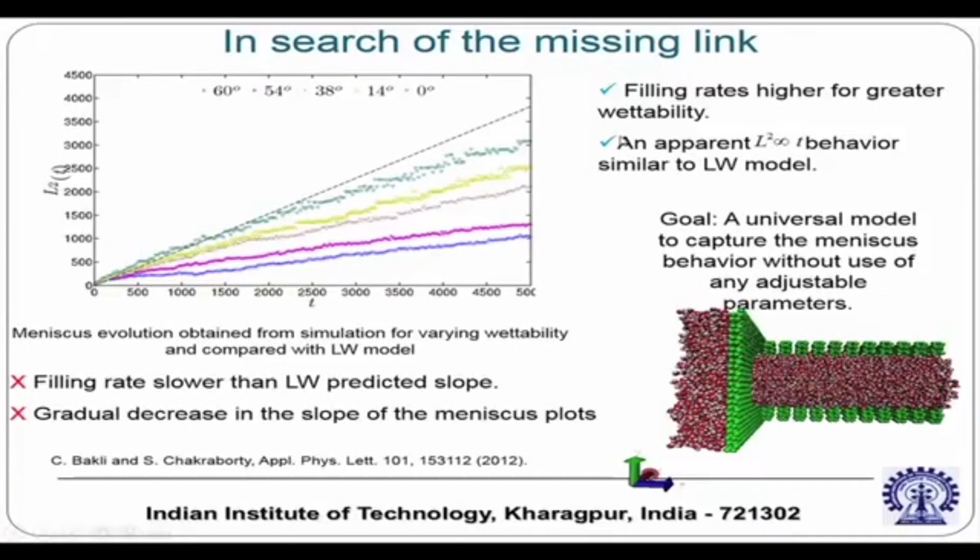However, one has to keep in mind that although the capillary action is stronger, you also have a resistance force, and the resistance force will depend on the slip, and slip depends on wettability. So it is a complex coupling; you cannot just give reasoning from a straightforward intuitive argument, because with wettability issues slip issues also come into the picture, and based on the slip you have the resisting viscous force.